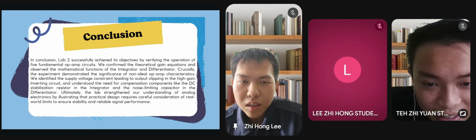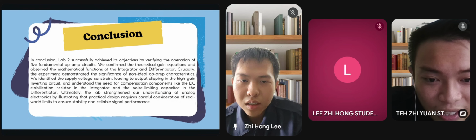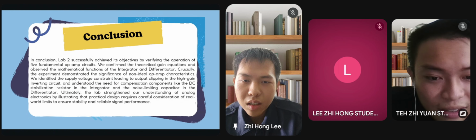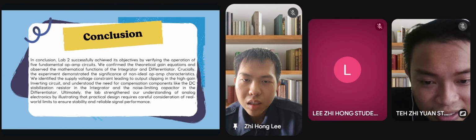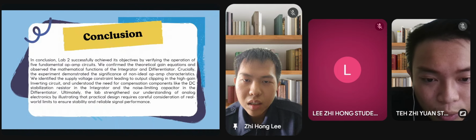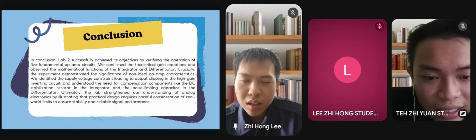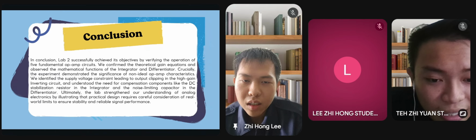We identified the supply voltage constraints leading to output clipping in the high gain inverting circuit, and understood the need for compensation components for stability and noise limiting.